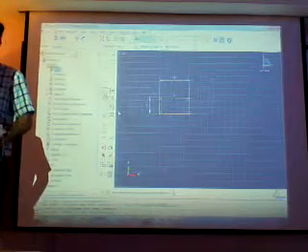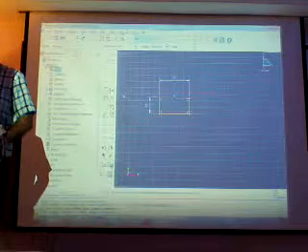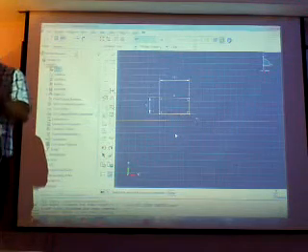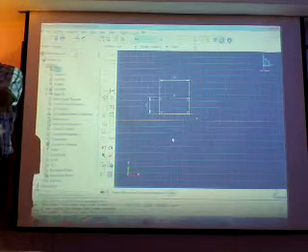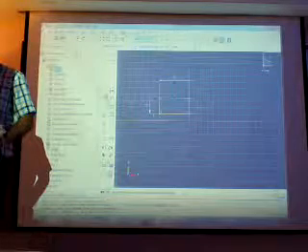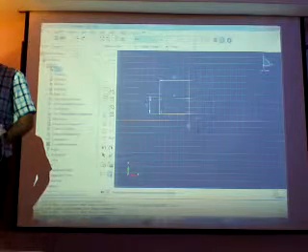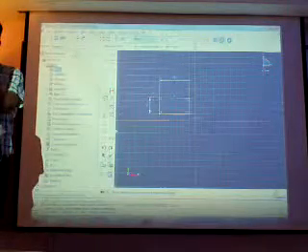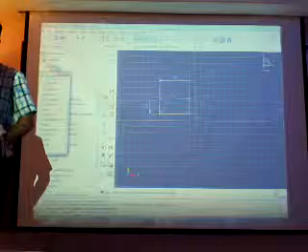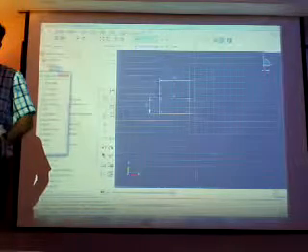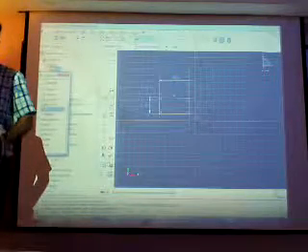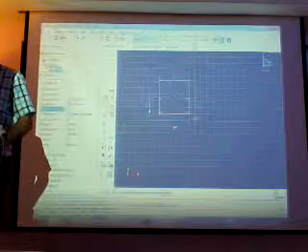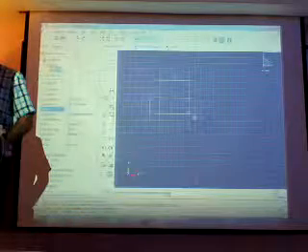If you have a complicated part, to make it easier for assembly or other things, you can also define the axis to help you for the next module, for example in assembly or interactions. And here you can define constraints, for example coincident, axisymmetric, fixed. First we fix the axis. Done, and another axis. Done.